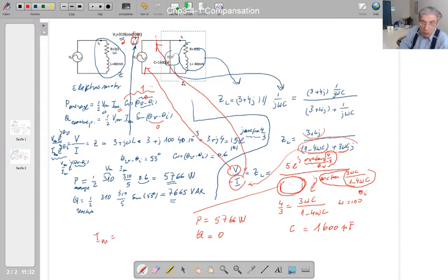is the square root of 1/4 omega c square plus 9 omega square c square. So I am saying this maximum current value here is going to be this one. But this I1 here is going to be the same as this I1. That means the electrical energy that I get from the supplier is determined by this current. Now this current has been reduced. If you calculate the current here,